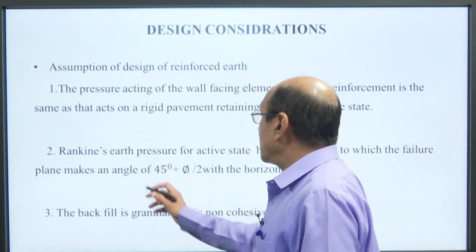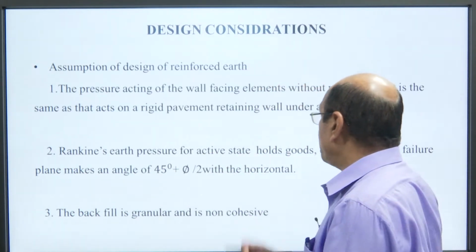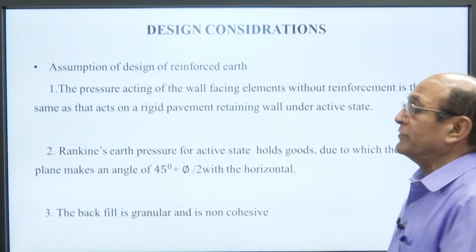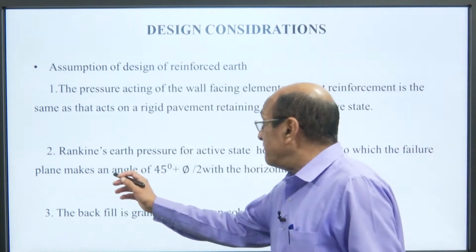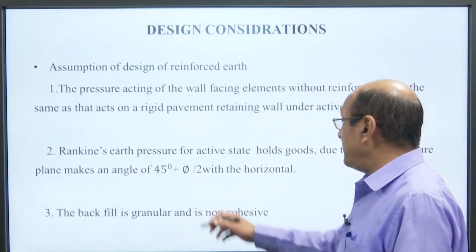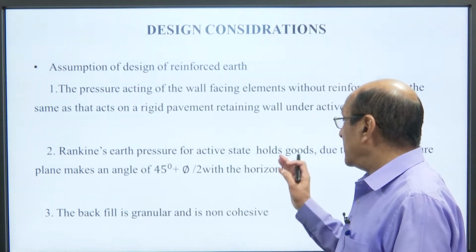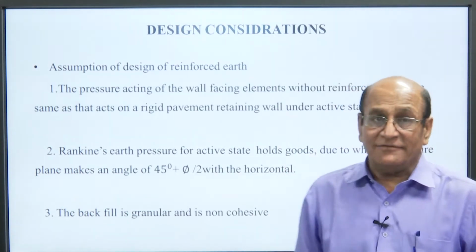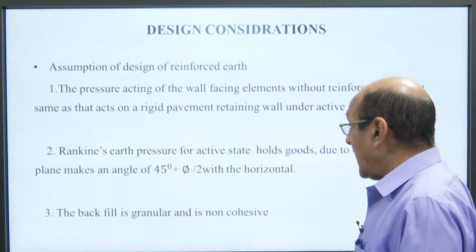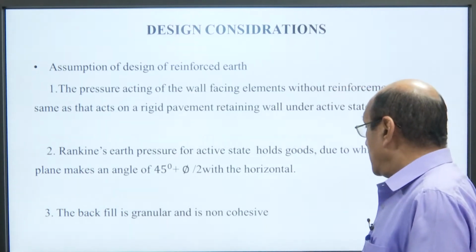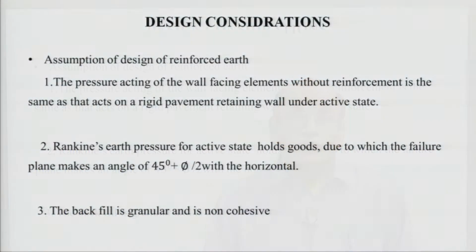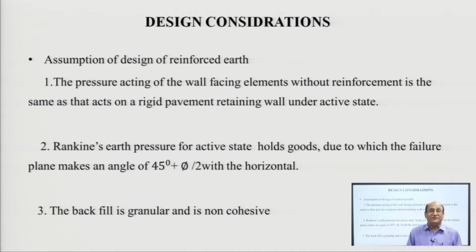The Rankine earth pressure for the active state holds good, due to which the failure plane makes an angle of 45 degree plus phi divided by 2 with horizontal. And third, the backfill is granular and is non-cohesive. So, these are three basic assumptions for design consideration of reinforced earth.